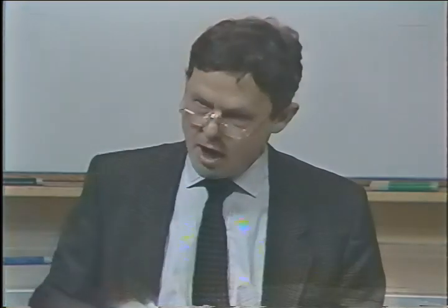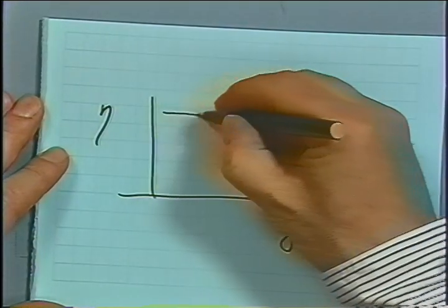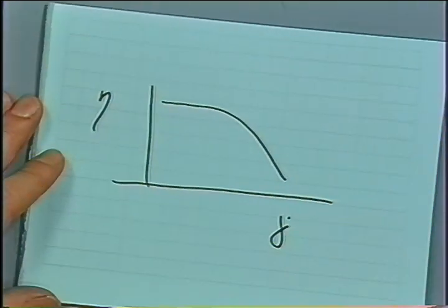It is a model. Remember, the viscosity function which we used is okay at high rates, but there's an error in this viscosity function at low rates of deformation, which occur in the center of the capillary. In a capillary flow experiment, we basically probe the flow. If you take the viscosity function versus shear rate, on a log scale, it would be this type of function.